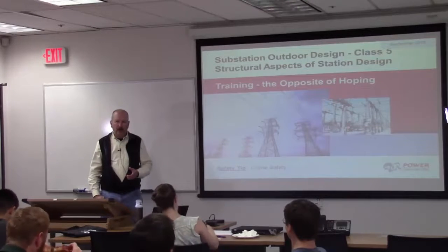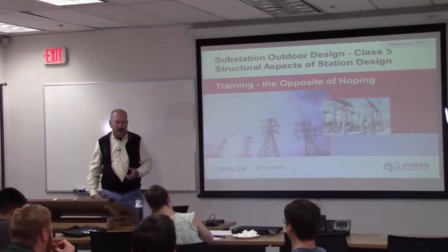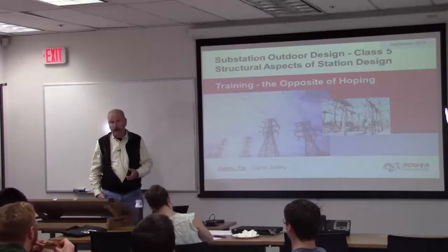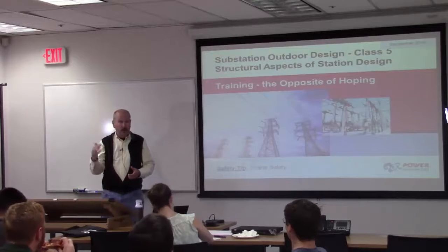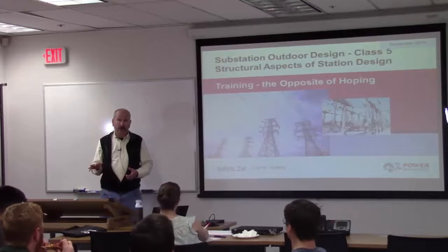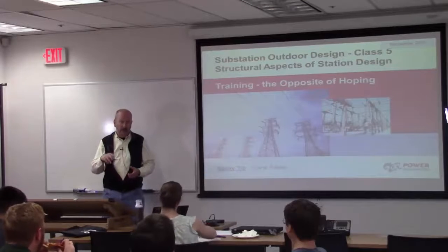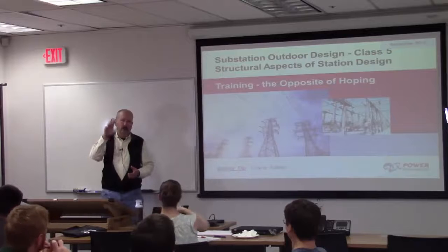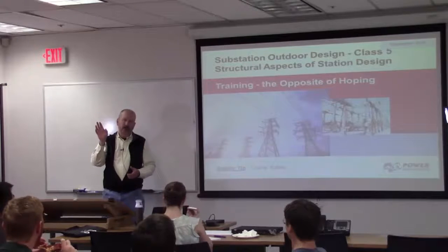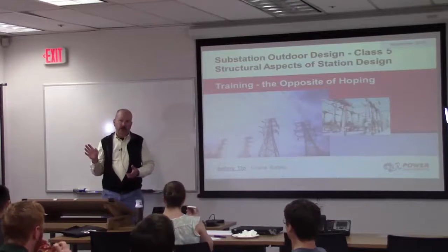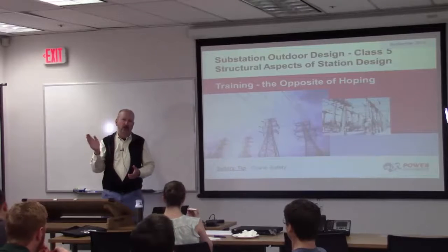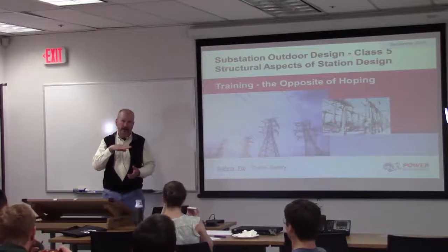And there's many ways cranes can have problems and end up hurting people. They can tip over. They also, if they have an inattentive operator, can lose control of the boom. Your rule of thumb of safety is that you're safe if you're more than a boom length away from the crane.